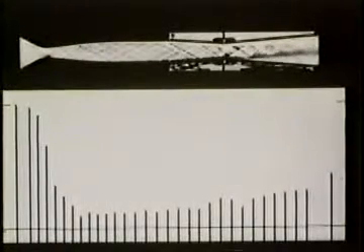The advantage of using an adjustable second throat to control the airflow is that the stagnation pressure losses and hence the power required to run the channel can be reduced below the requirement for starting.